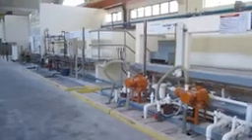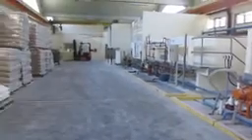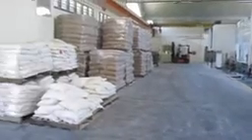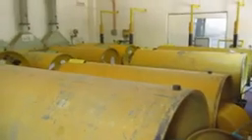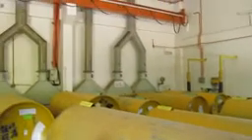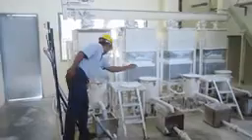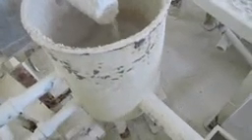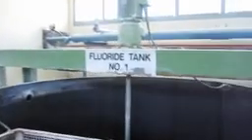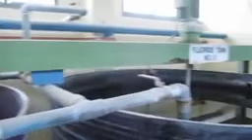In the clear water tank, the water is disinfected to destroy microorganisms which still remain in water after filtration. Chlorine compounds are normally used for disinfection. The pH is adjusted using hydrated lime. Fluoride is also dosed into the treated water to prevent tooth decay.